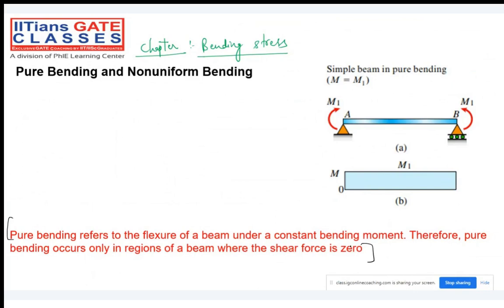Yeah, correct, correct. What are the answers you're getting? You can solve that particular problem by this one. We need to find the reaction force at point B. If you are getting the deflection because of wL^4 divided by EI, and it is exceeding this particular gap, if it is more than 6 mm, then the reaction at B will not be equal to 0.